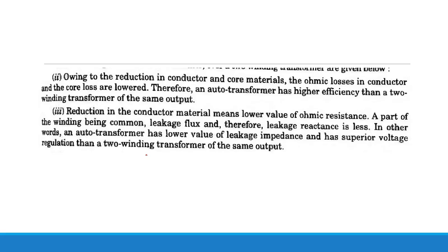Can you use this transformer at all times in place of a two winding transformer? We said it is preferable when your voltage transformation ratio is near to unity, at that time it is a better choice.